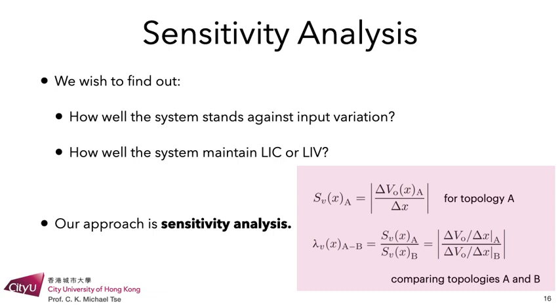The idea is to compute the variation of, for example, the output voltage with respect to variation of a particular parameter. For example, if X is the input voltage, then we are trying to assess the sensitivity of the variation in the output against variation of the input voltage.